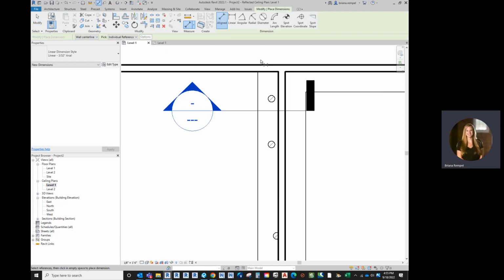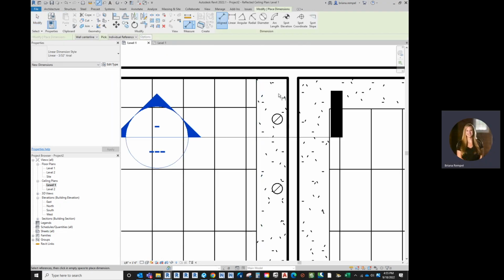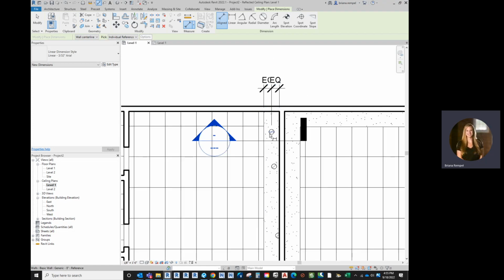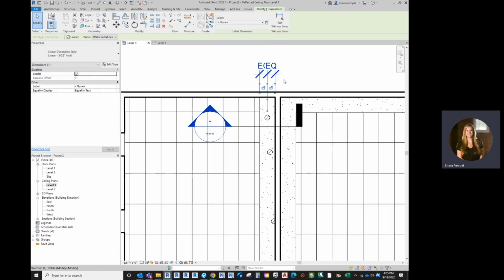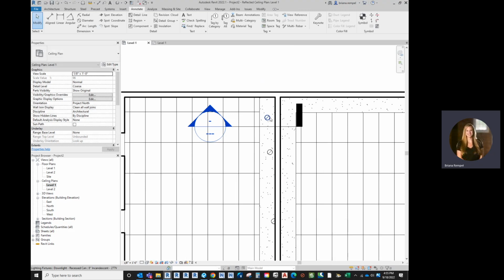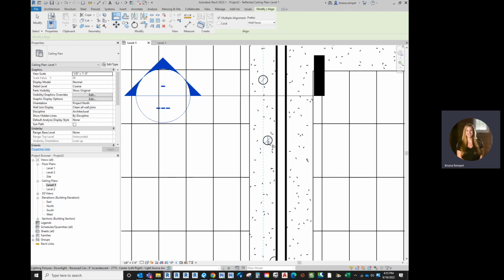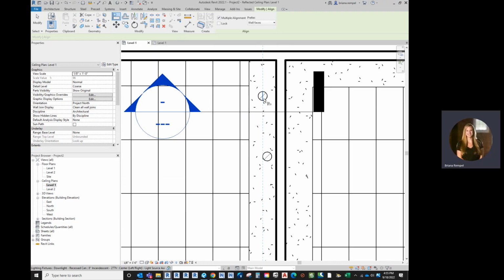I like to use the dimensions to help do that. So just tabbing to be able to select what I want there. And there is a center line in here. So if I get one of these set and I see it equals, now it's equal between the edge of the soffit. I can unconstrain that. But then I can use that in the line tool. I'm typing A there. That's a shortcut that I have set up for a line. The default shortcut is A. So there you go. So it's A, and then first click is what you want to align to. Second click what you're aligning.